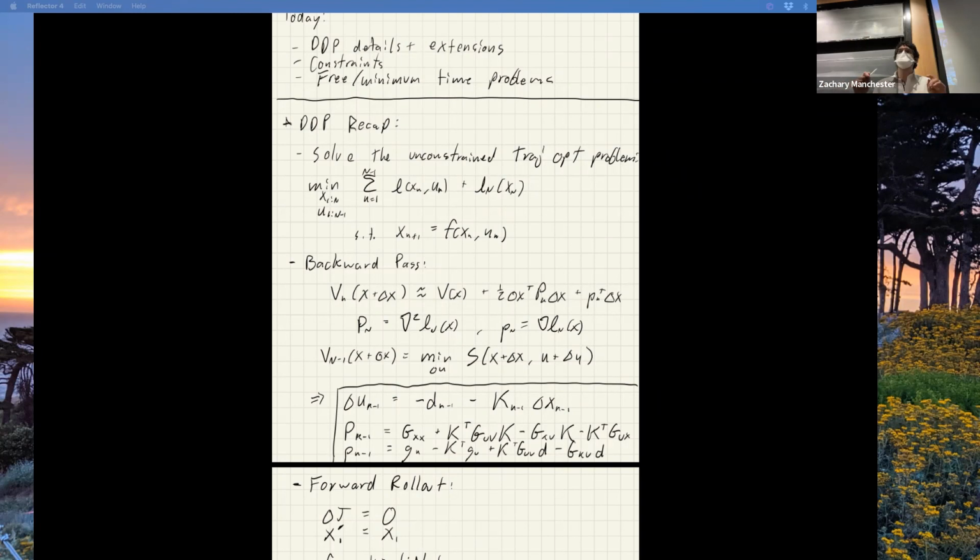So really what it's doing, one way to think about this is it's iterative LQR. It's basically going to linearize that and turn it into an LQR problem and apply the LQR stuff to it, and then iteratively relinearize and resolve it using an LQR approximation. So just like LQR can't handle constraints, right? That's the way to think about it. Does that make sense, everybody? Anybody else have any questions?